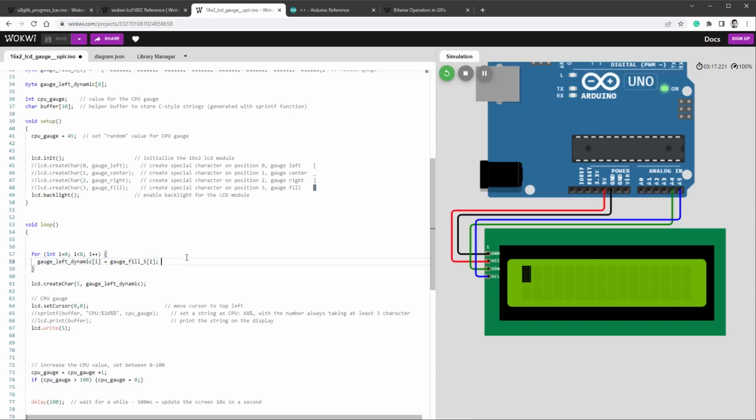There is another way, and this one is that you can imagine that this is the display content and this is our 1x1 array. And by default we assign it like this, so every pixel will be filled. But what we can do is we can shift everything to the left side, and in this case, if we shift it by 1, this left side will not be even visible, so there will be an empty column on the right side. If we shift it by 3, we will show 2 columns being filled and 3 not being filled.